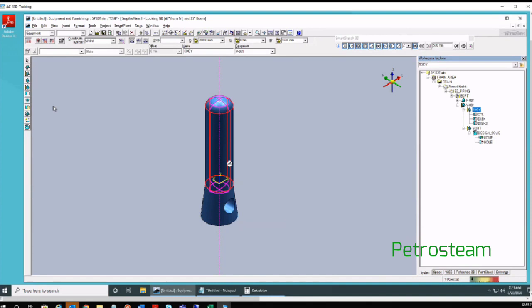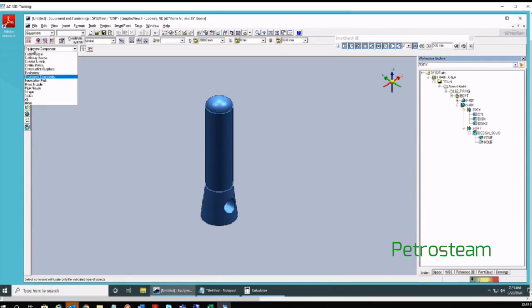Like this, there is a locate drop down available, and it is as per the task you are working with. Similar to the toolbars, which are set as per the task, the locate drop down will also be available as per the task. In this, you can go by equipment, equipment component, or shapes. If you want to select only shapes for modification, you can select shape.